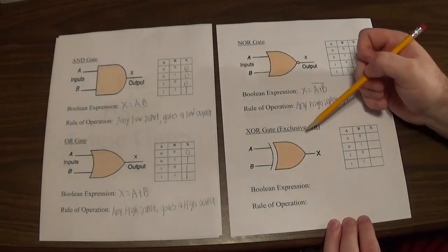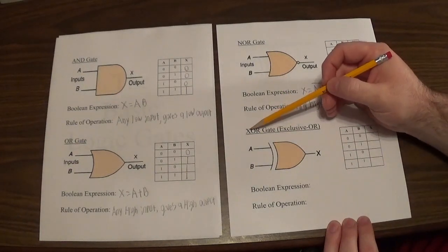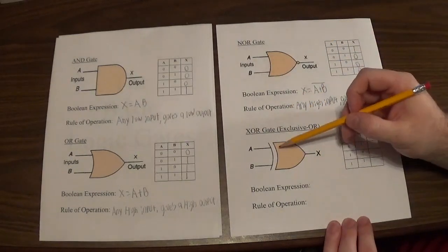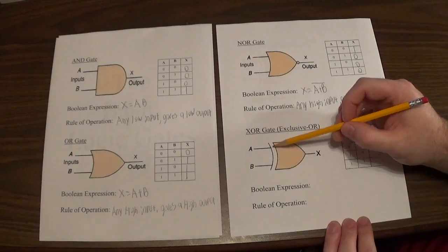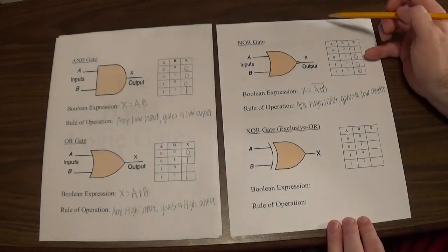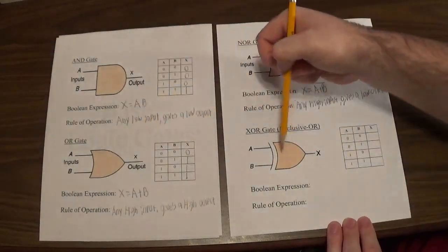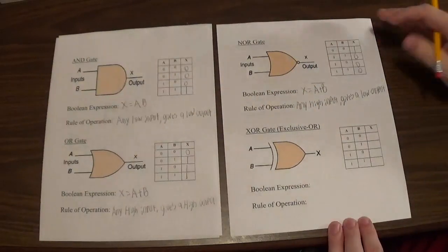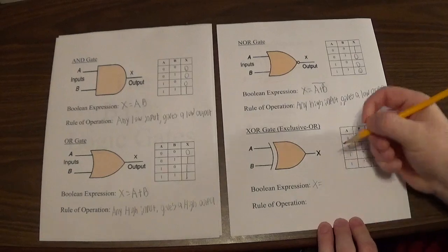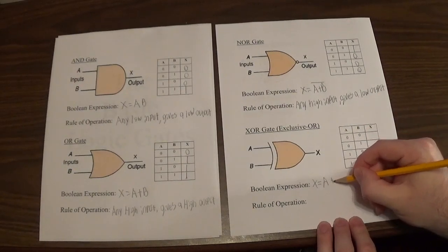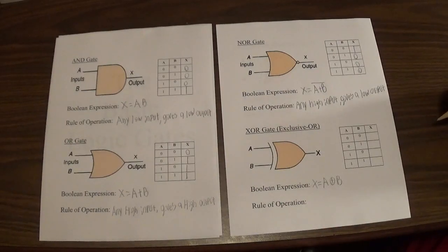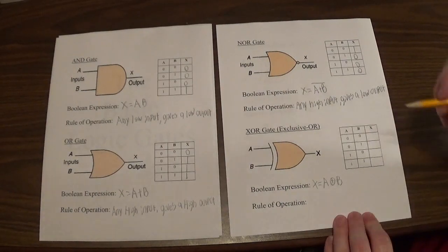All right, so it's an exclusive OR. We abbreviate that as just an XOR gate, but that stands for exclusive OR. So the way the symbol is done is that you have this space here on the inputs to an OR gate, and that's what makes it an exclusive OR. So you can see the comparison of just a regular OR and an exclusive OR. All right, so the expression here, X equals A exclusively OR B. All right, so that's how we write it as a Boolean expression.